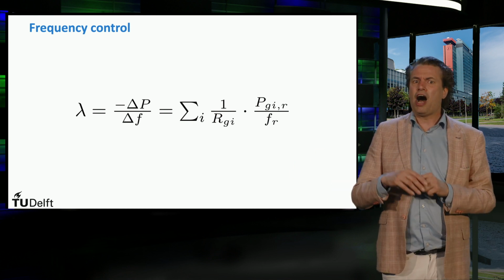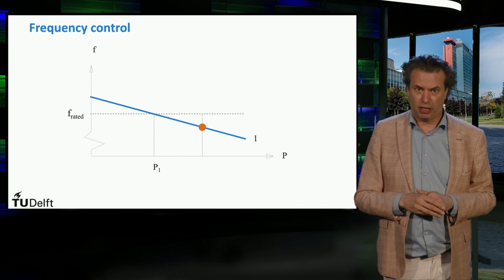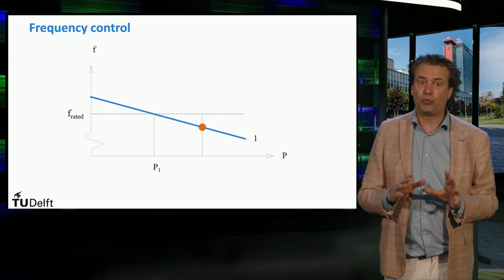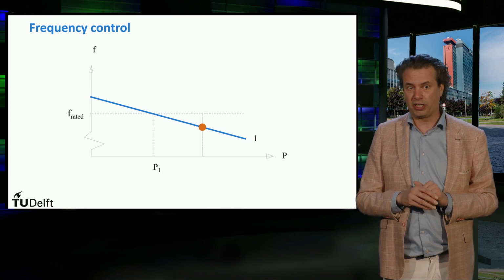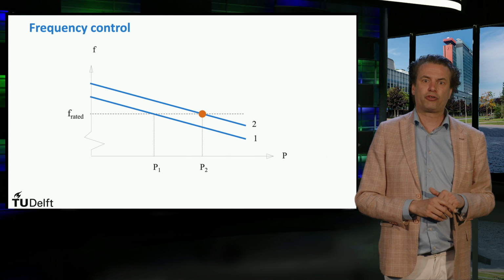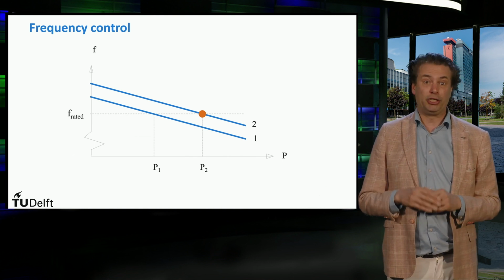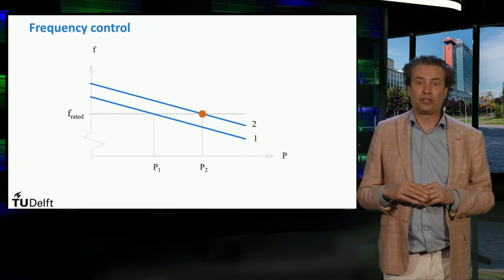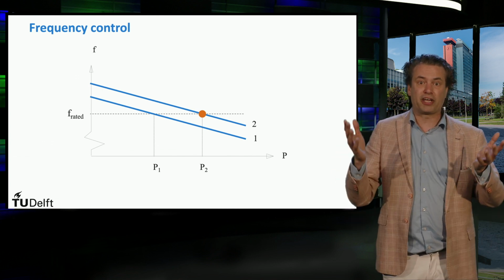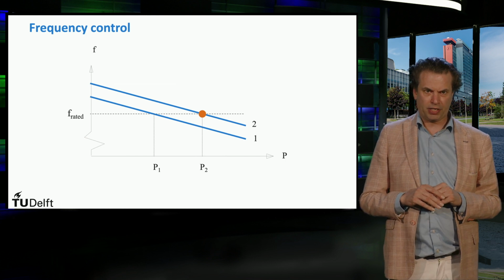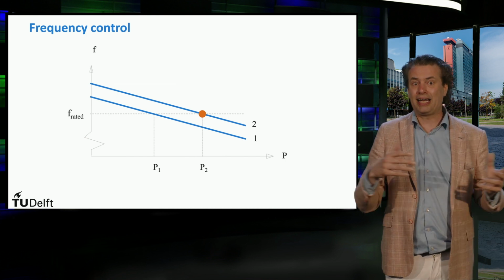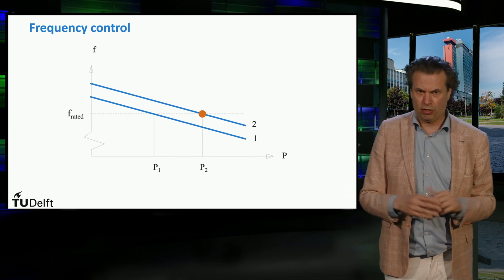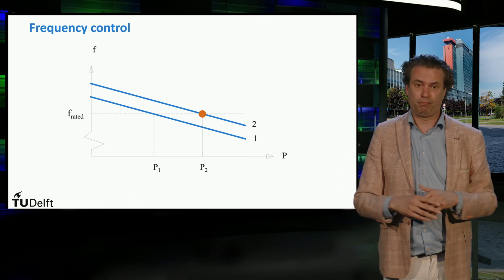What does it mean? After primary control takes place, the power balance is restored at a lower or higher frequency, which is not a desirable operating condition. Secondary control brings back the system to the original frequency by temporarily increasing the prime mover power, which raises the kinetic energy and therefore the frequency of the generating unit. It also allows bringing the tie line exchange of power back to the one that was agreed between the areas. An area can be a country, for example.